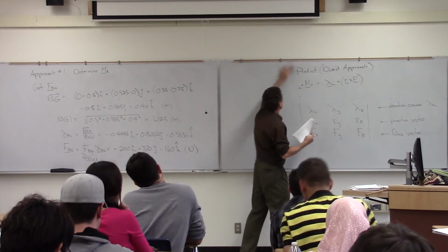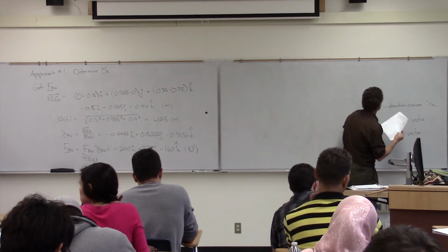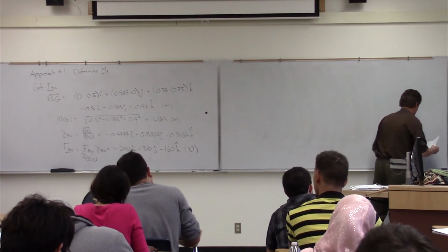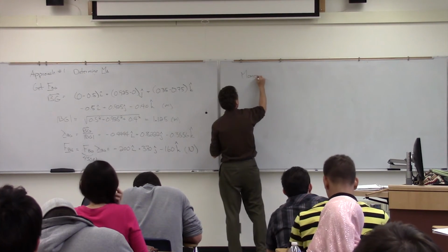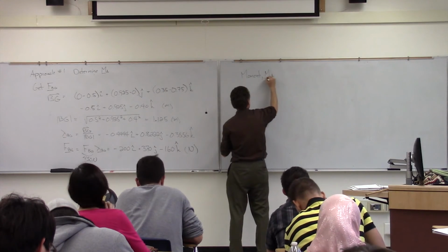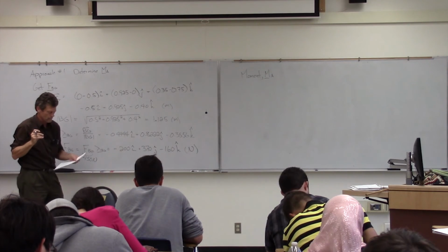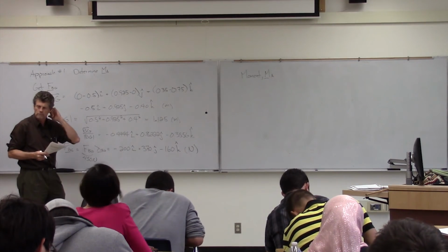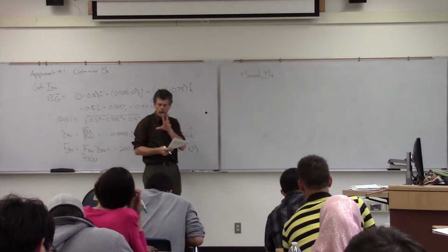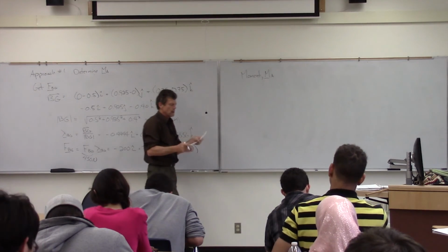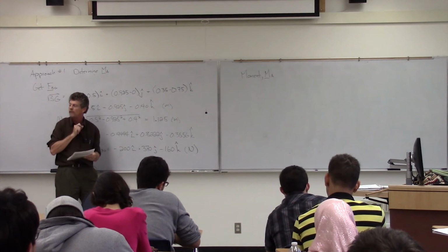OK, so remember our cross product. What we want to do is set up that little determinant. So calculating the moment, what we need now is an R vector. Can anyone see a nice R vector to B? No, it's from A to B, right? So what we want, A to B or A to G. Again, those are 2 points on our line of action that we can find real easily.